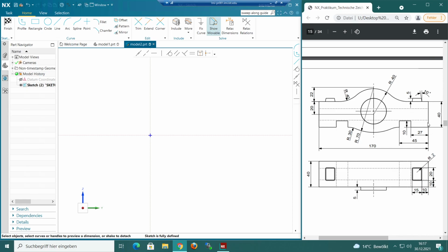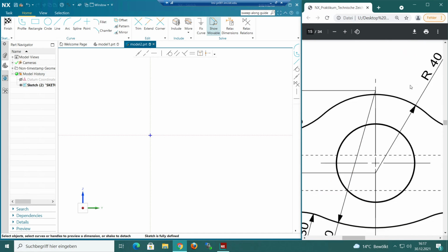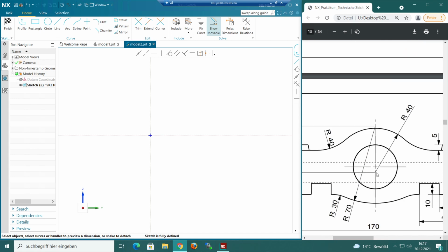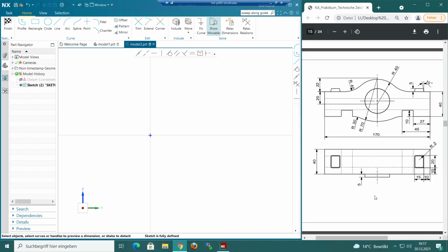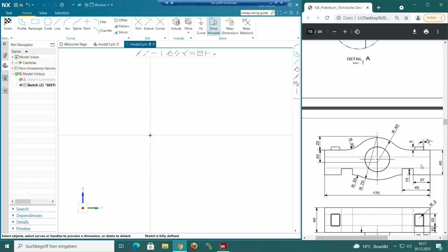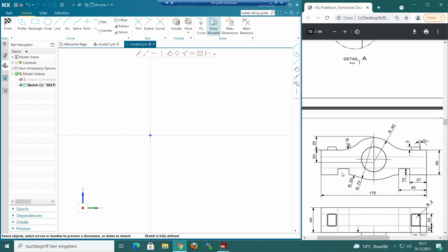You can see 40 millimeters is the dimension of this straight part, and 20 millimeters, half of it, is right here, where a radius starts. That's not the same as the middle point of this round thing, but that's no big deal, because we will model that later on. That's not part of this sketch, because that's a different extrude. And right now we are not concerned about that one, and that's why I would say that we will want to have our middle point exactly here.